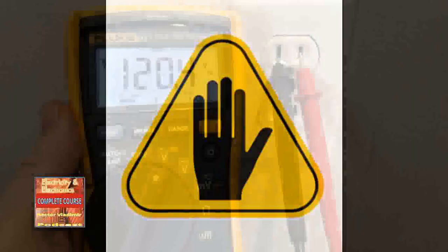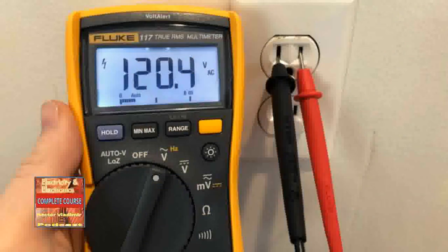Caution. When using a multimeter or DMM, it is easy to connect the meter to a voltage source immediately after taking resistance or current readings. This is the most common mistake when using a multimeter or DMM. This action will result in damage to the meter or personal injury.